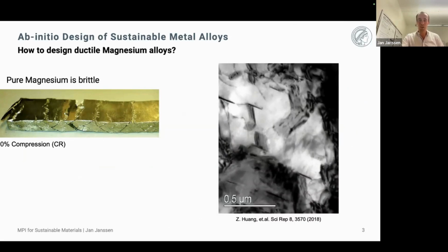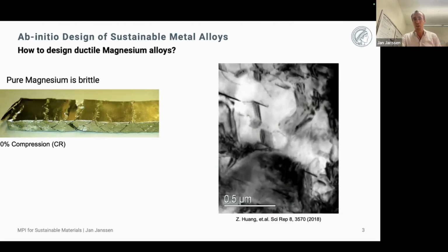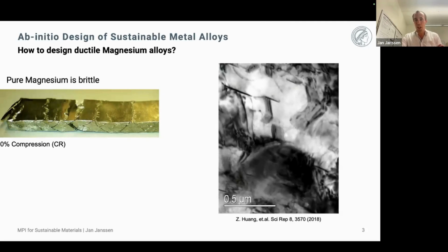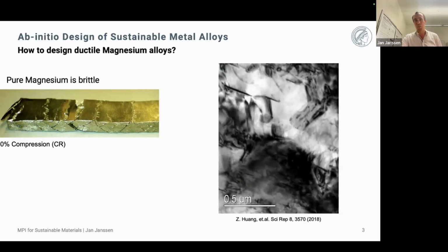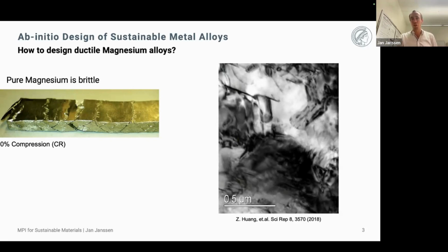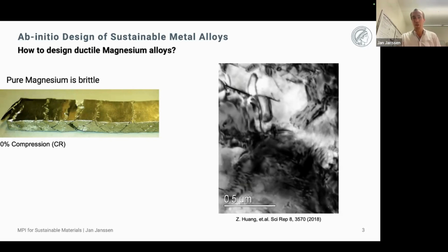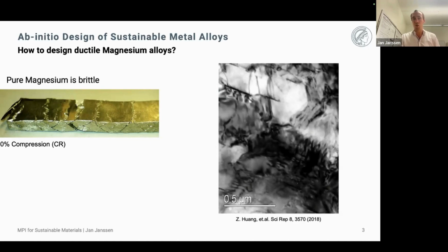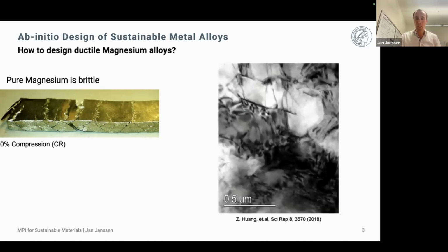The reason for this is what is known as dislocations. You see them as these black lines moving through our material. As long as they move, they are not so bad. But when they stop at a specific point and more dislocations pile up at this point, that's when it fractures. So that's where we get this brittle behavior from, and then the material can't be used.